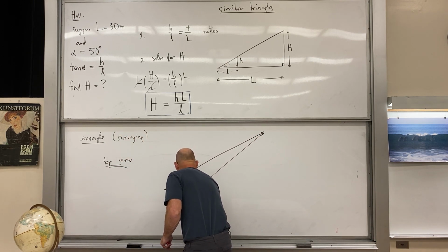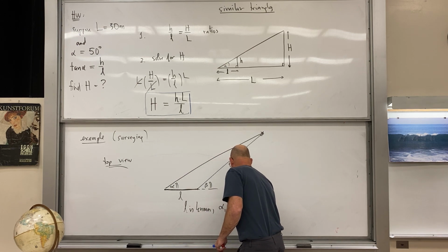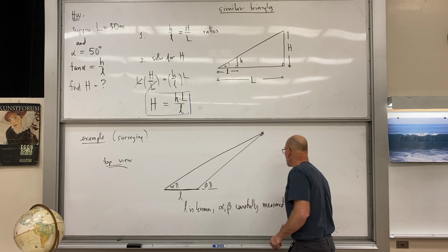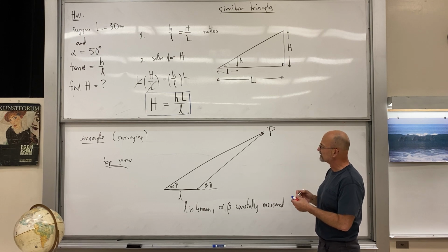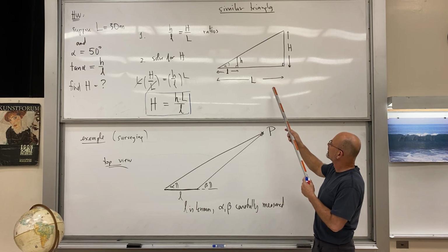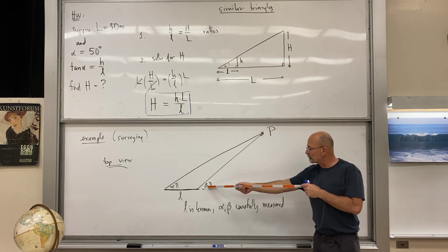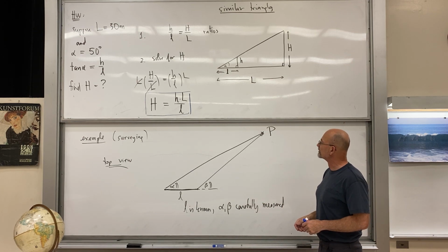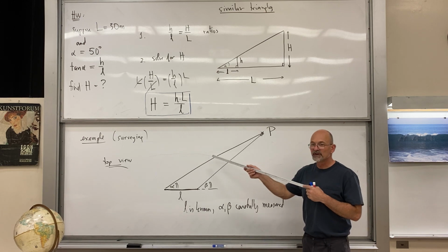So L is known, alpha, beta, very carefully measured. And then this location, point P, can be located exactly. Okay, so that's what the surveyors do, and you recognize they're not quite using these similar triangles, but they're just using some trigonometry as well. You could, in fact, build this up out of similar triangles if you have a little patience. Good. Actually, similar triangles wouldn't be the method here, but you could build it up out of triangles.